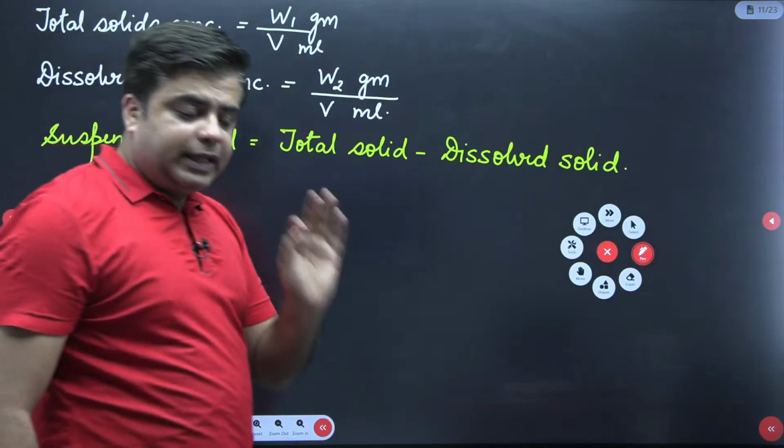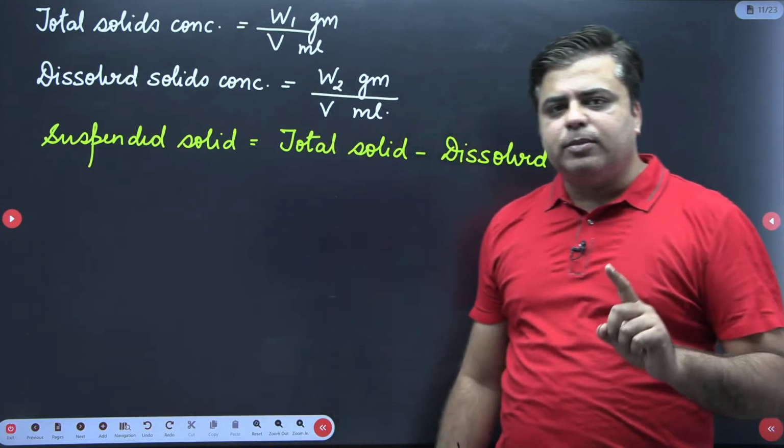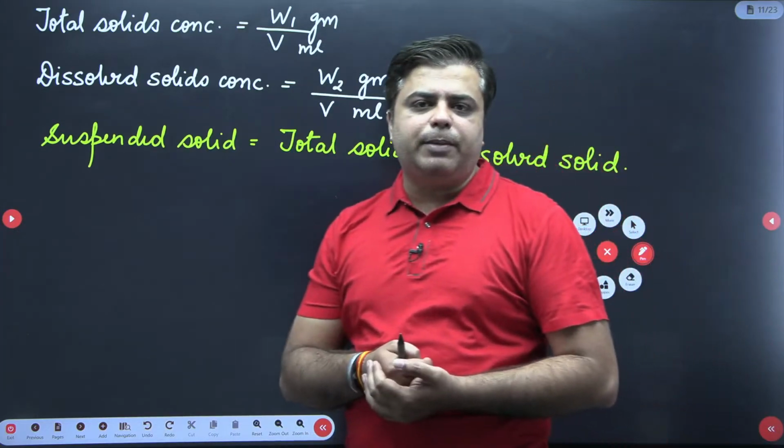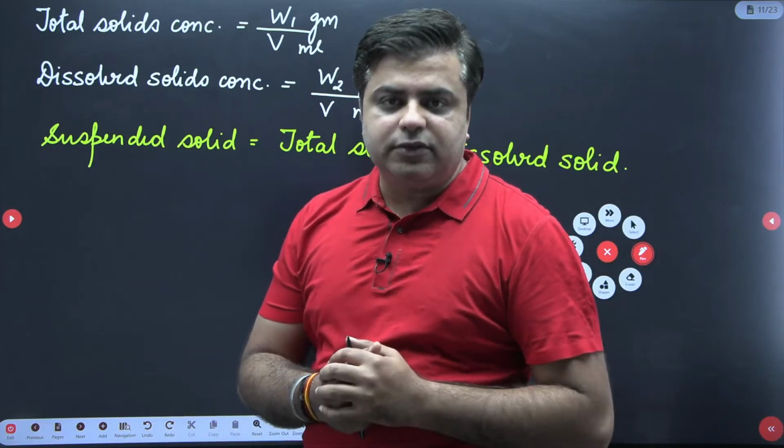We never keep the filter paper in an oven. The reason is, there is a possibility that the weight of the filter paper may change, and that eventually produces error in the calculation of suspended solids.